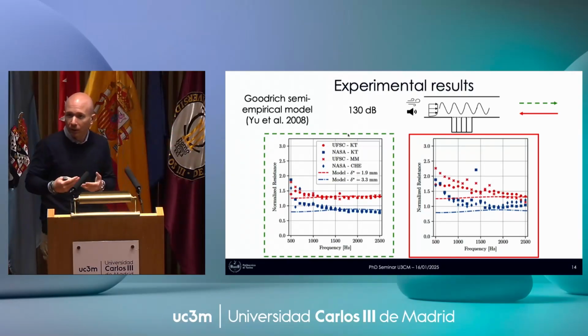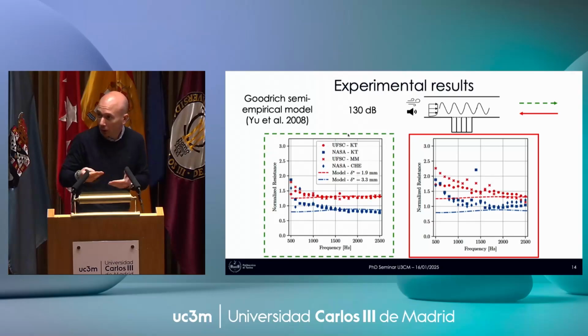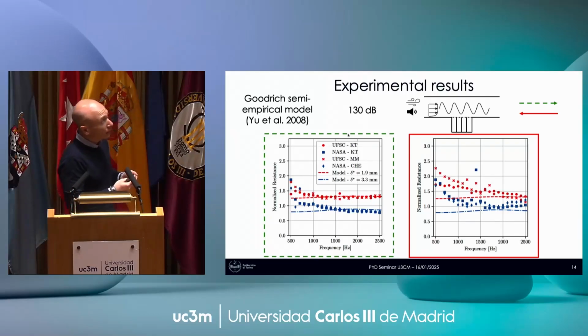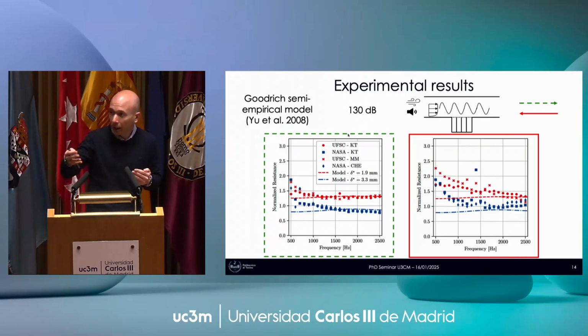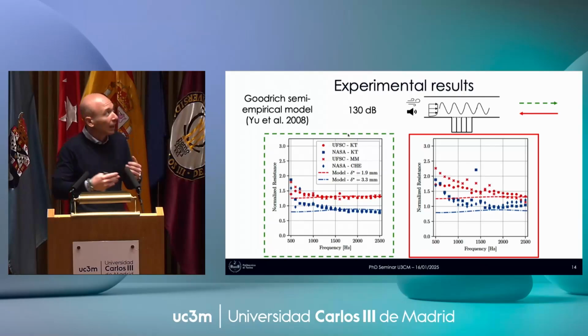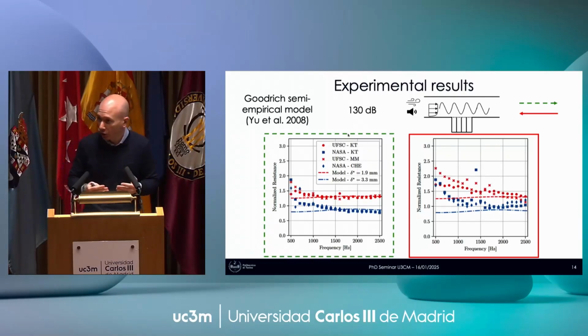So this confirms from one side what we found out, add another variable that is the impact of delta star on this phenomena, and add other considerations. Another consideration is that, okay, when we have the acoustic source in direction opposite to the mean flow, also the scatter between the different techniques is larger. So what are we really comparing?